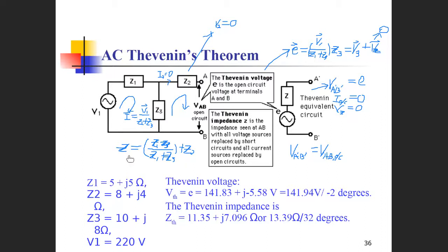Okay, so you can see that we use the same forms as for the DC circuit for easy understanding. This just shows in principle that Thevenin's theorem is the same as that in the DC circuit. But we have to take care that the impedance, voltage, and current here are all in complex number forms. So this is the internal equivalent impedance and internal electromotive force relationship between Z1, Z3, Z2, and V1. Suppose Z1, Z2, Z3 and V1 are given, with V1 as the reference.